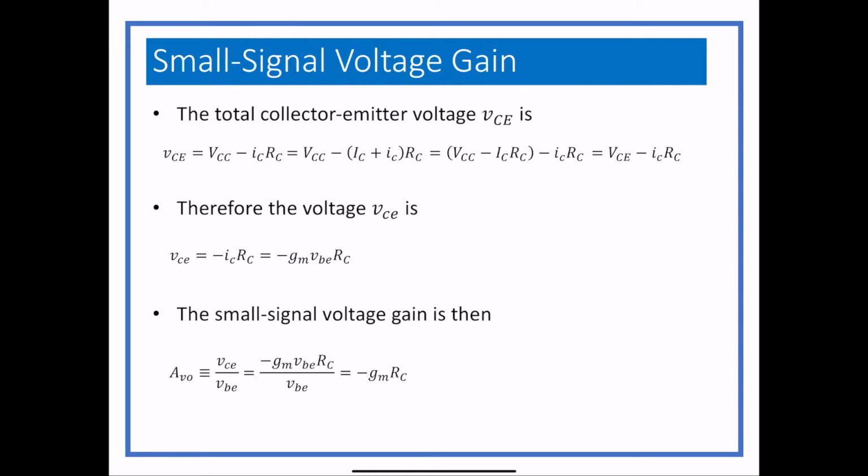It won't always, depending on the configurations we use, we won't always end up with a transconductance term. Sometimes we will end up with ratios of resistors because we have alpha and beta that can relate these resistor values. So sometimes we end up with equations that don't include GM at all and don't look like MOSFETs, but this one does. This one looks a lot like a MOSFET.